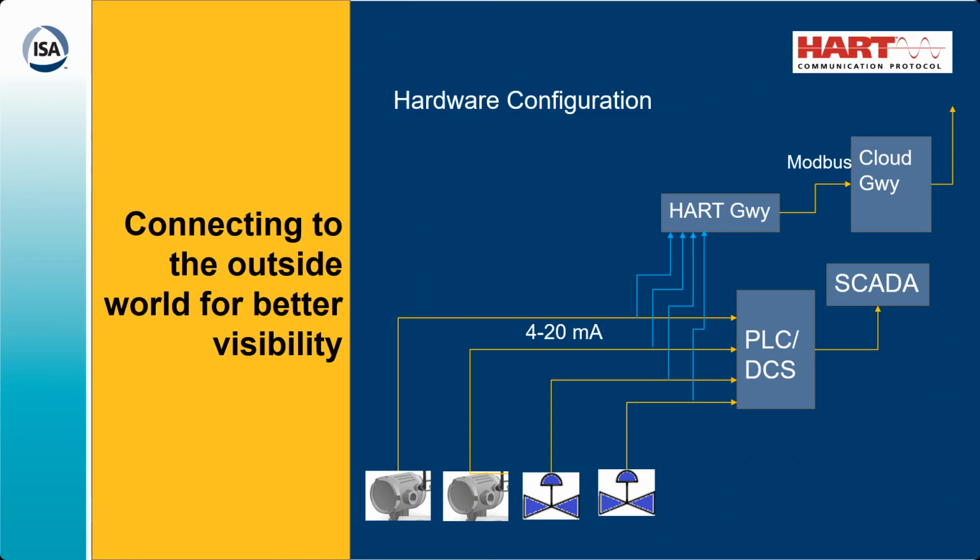If you use the HART gateways directly, you have a little more cost benefit, and if you don't have the HART enabled gateway in your plant, you don't have to invest in that. You can use it without making any additional changes in your plant. You can just employ this and connect it into your panel, to your key process parameters.